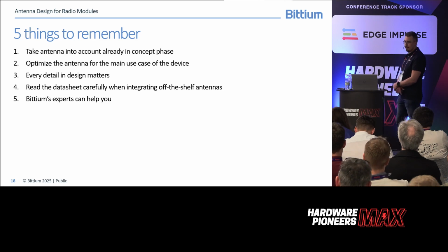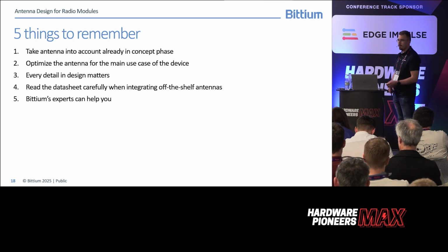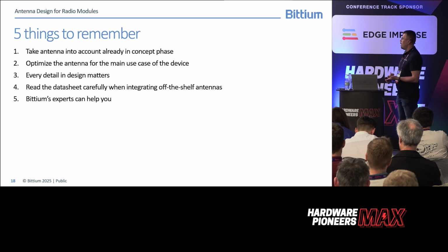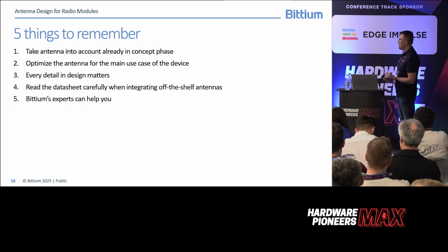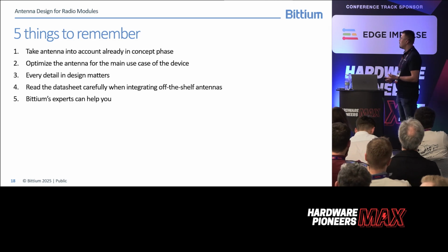Every detail in the design matters: grounding points of the metals, lengths of slots and metallic parts. And read the datasheet carefully when integrating off-the-shelf antennas.